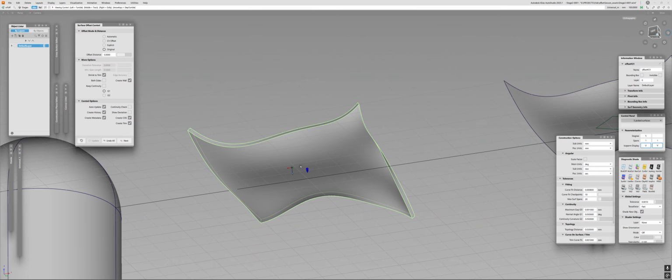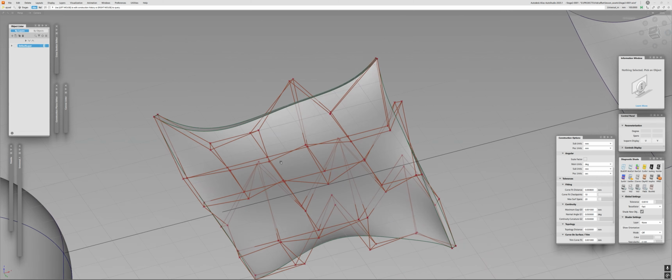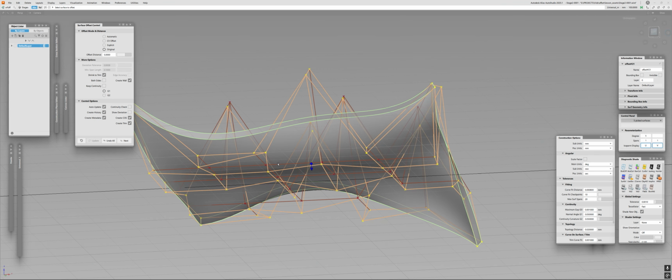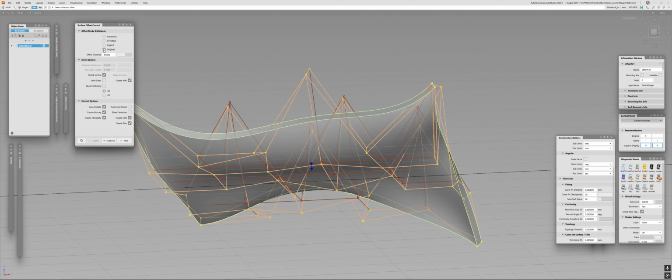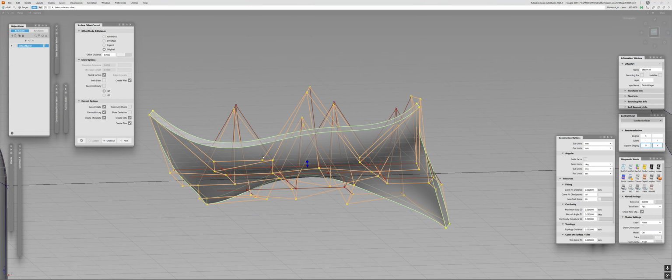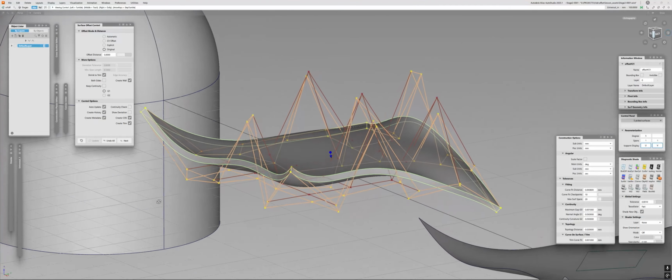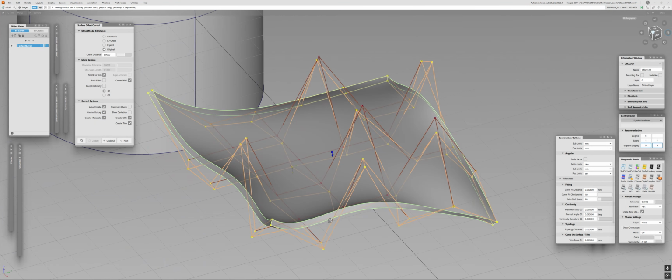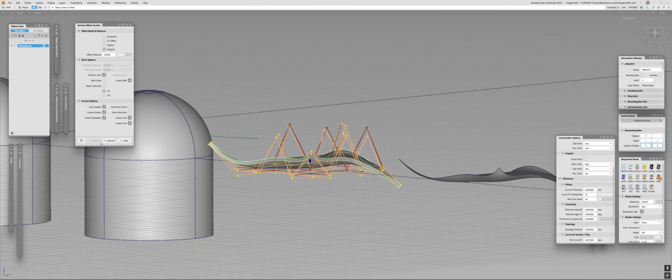Now, we can, of course, try to use the original, and you're going to see that the result will be quite the same, but it's shifted a bit. Because original, you're going to see, I'll click on the CV offset. It's just an offset on the normals of the CVs. Original, if you remember, I already mentioned, is part of the automatic process. So even though it takes the same parameterization, it will not guarantee that the points will be in the normal direction. It just tries to make a somewhat decent, somewhat equal gap between the two. So I would say this is not really very beneficial in this case, right?